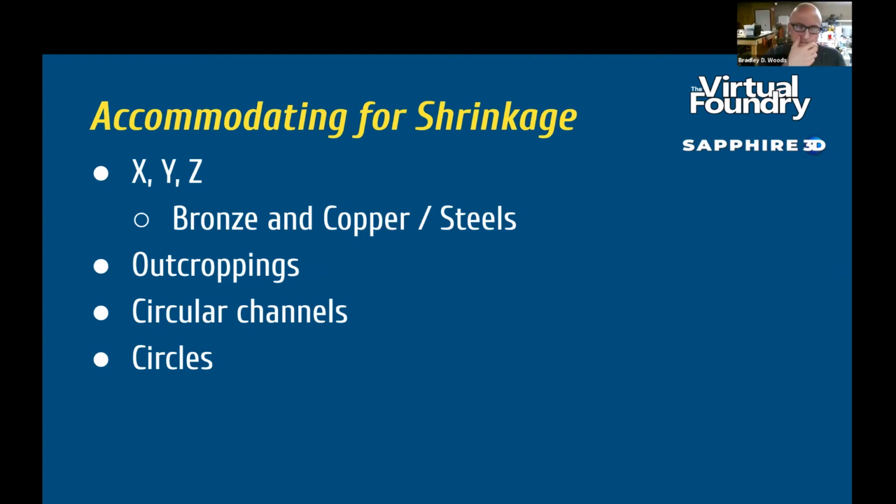Right. And this might be helpful to some people as they're trying to envision this. The force that drives the shrinkage is actually surface tension. Some people call it atomic diffusion. So it's the particles welding to one another, and then it's the power of the surface tension that causes the whole part to shrink. So that being said, you can actually control the amount of shrinkage.